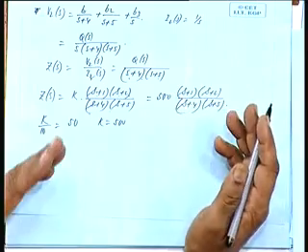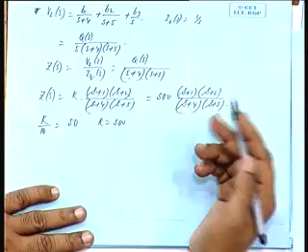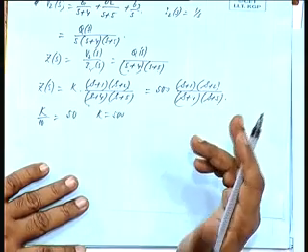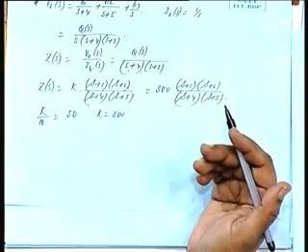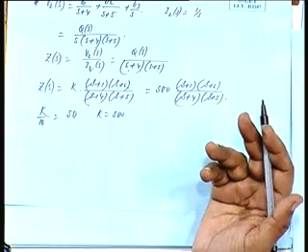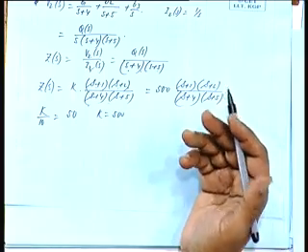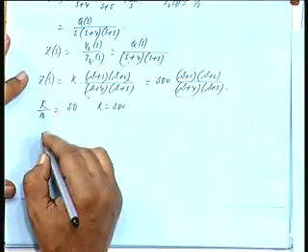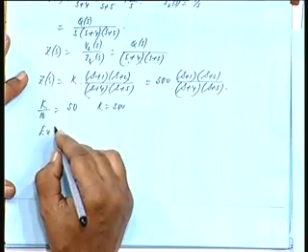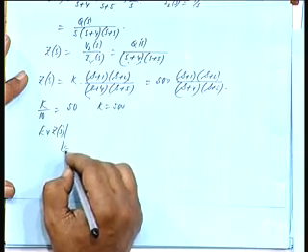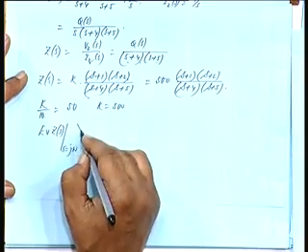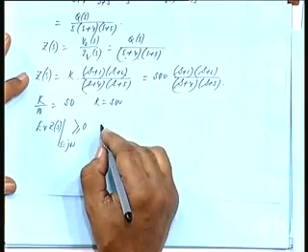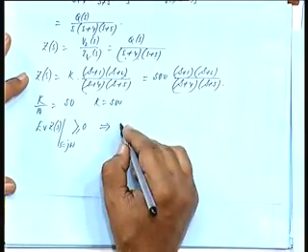Roots are in the left half plane, then the degree difference is restricted to 1, all those conditions are satisfied. But no, that is only for RL or RC, it can be an RLC synthesis, that is possible. So, we are not concerned about that. The test that you have to make is even Z(s), if I put s equal to j omega, should be greater than or equal to 0 for all omegas, is it not? So, let us find out the even Z(s).